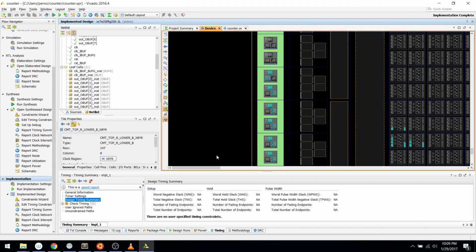The next thing we want to do is get on top of the timing. Now, this is a very simple circuit, but there's still limits to how fast we can clock it. Right now we've used the CLK clock line in a way that implies it's a clock, but we haven't really told the system about the clock. In reality, the clock is going to be an off-chip oscillator of some sort, like a crystal with an oscillator. It's not hard-coded into the FPGA chip what frequency it's going to oscillate at. It's going to be driven off-chip.